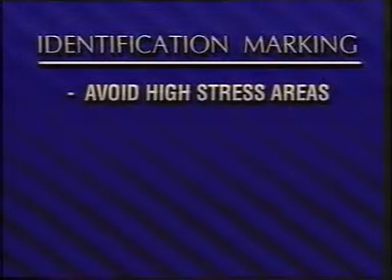Identification marking on components can introduce excessive stresses. The location and method of marking this information is particularly important. Marks should not be in areas of high tensile, bending, or torsional stresses.